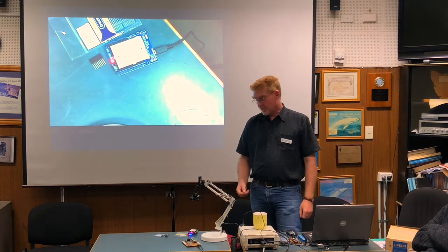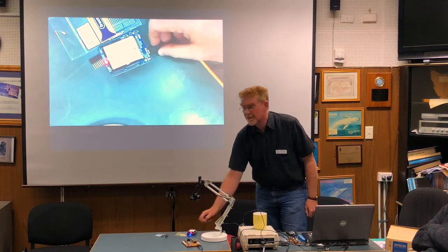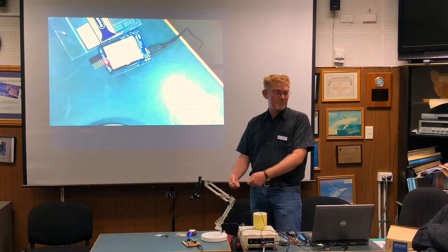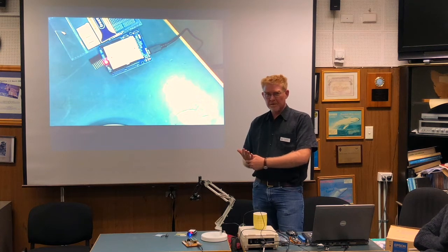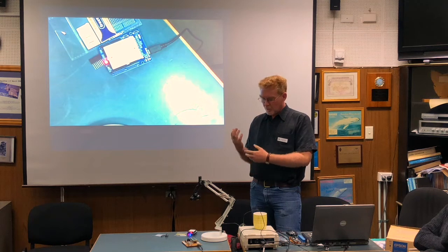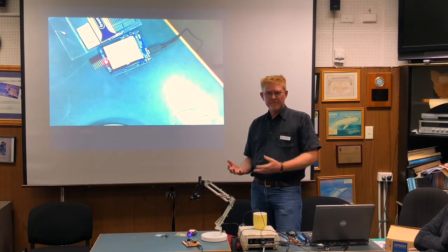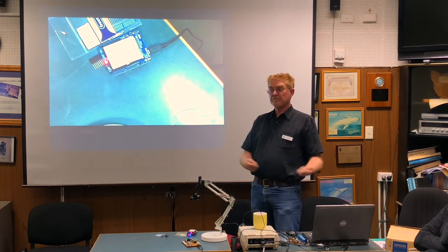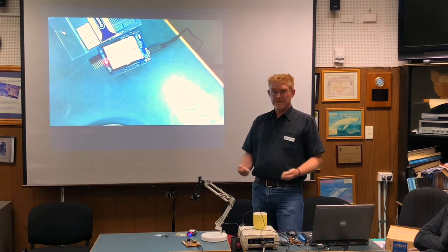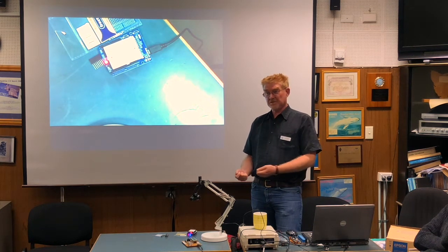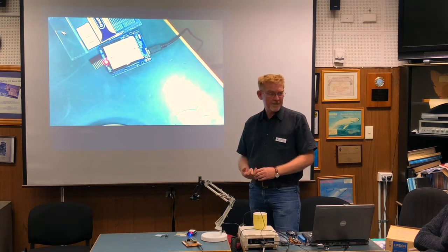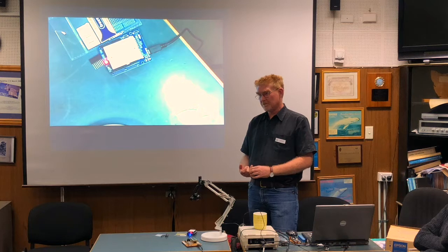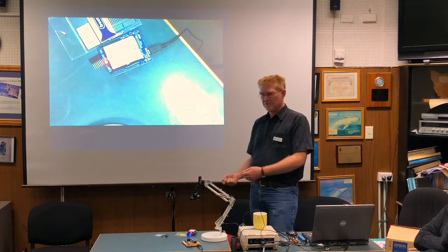Also, the other problem you've got with these is that it's a USB connection. How much power can the USB connection provide before bad things start happening? That can be both practical and software and hardware. When you connect the USB device to your computer, that device tells the PC how much power it's going to draw. And if the PC decides that's too much, it won't power the device. Or if you pull more power than you say, it can blow the fuse on the USB port. You've generally got to turn the machine off, let the fuse reset and try again.